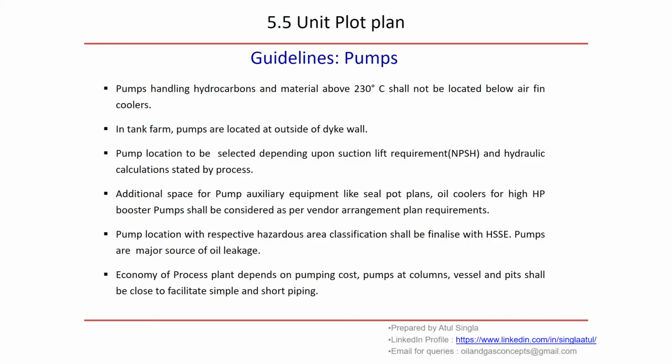Pump location with respect to hazardous area classification. This information comes from HSE, so we need to ask the HSE team also. Pumps are a major source of oil leakage, so based on these leakages HSE gives some recommendations. We need to consider all these recommendations to finalize the location of the pumps.